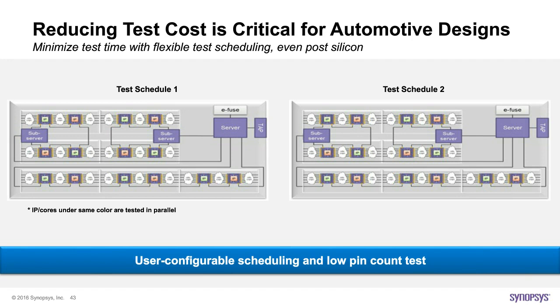In the mission mode, the difference is that I'm running functional mode and test mode simultaneously in different blocks. There, the power calculations and the test time allowed are different. Therefore, the scheduling is very different in building up my mission mode self-test activity for the permanent faults that would happen during the life cycle due to aging or other factors. And there, again, the scheduling will become critical.